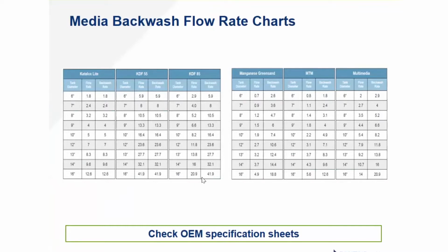If you need higher backwash flow rates, the 2815 stainless steel valve has one of the highest backwash rates we have, and those will work on substantially larger tanks in a single tank application. If you need alternating, that's something you can do with that size, but it's going to require an external valve to act as a standby that'll need to be programmed. So really, that's a water chemistry specific question.